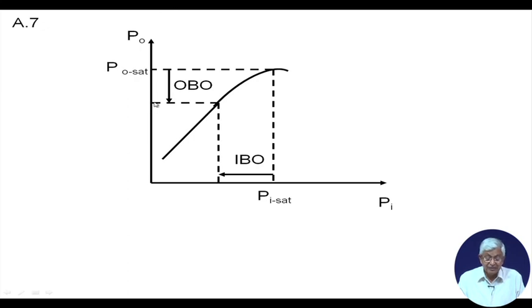So, the downlink side will come out clearly, but it is not given in terms of power input and power output, it is given in terms of input flux density, power flux density to EIRP, and we know that relation, that input power is proportional to input flux density.